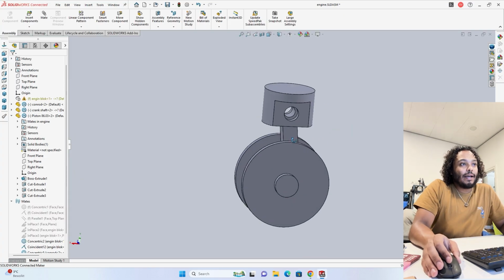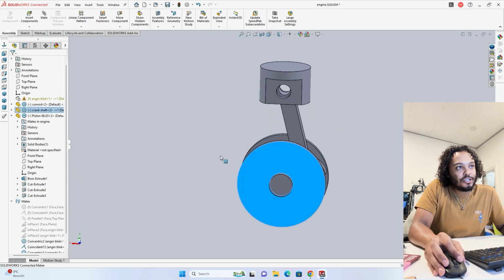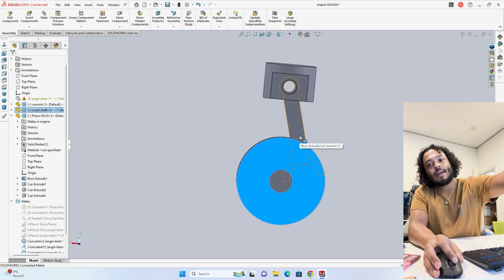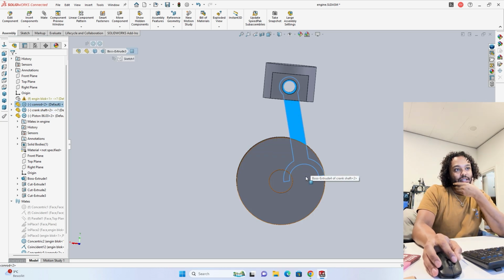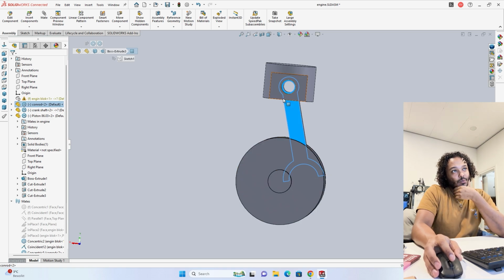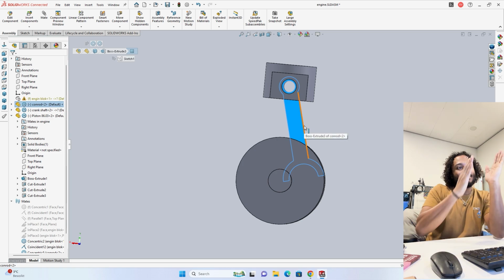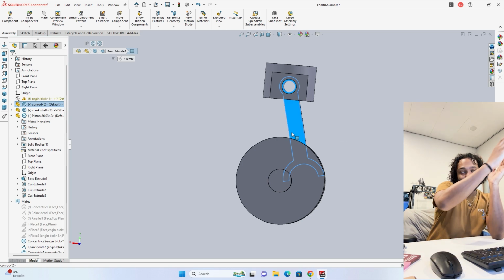So just to highlight and showcase why the connecting rod ratio is important, basically what it does is, if you have a taller connecting rod, as you can see on the screen here, so if the distance between where it connects to the crankshaft and where it connects to the piston gets larger, then the angle at which it pushes against the sidewall changes.